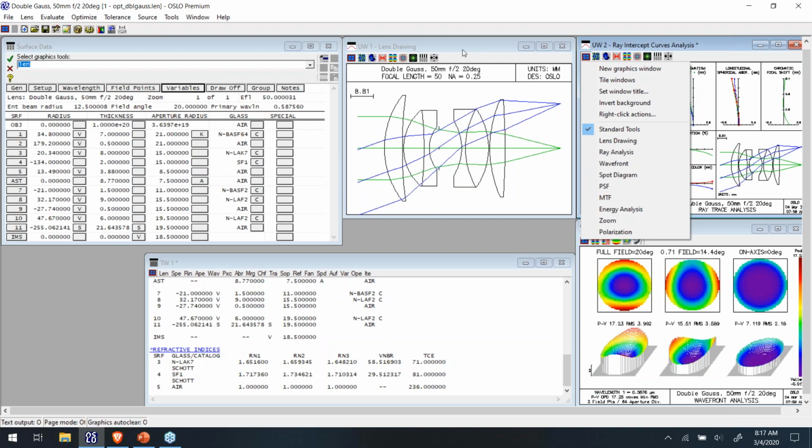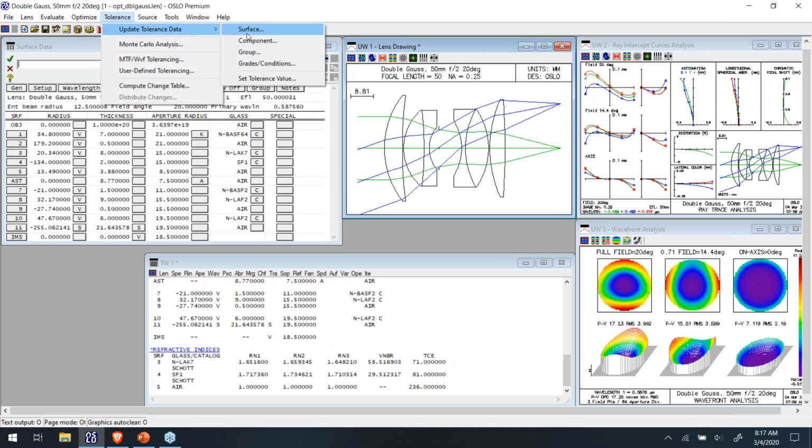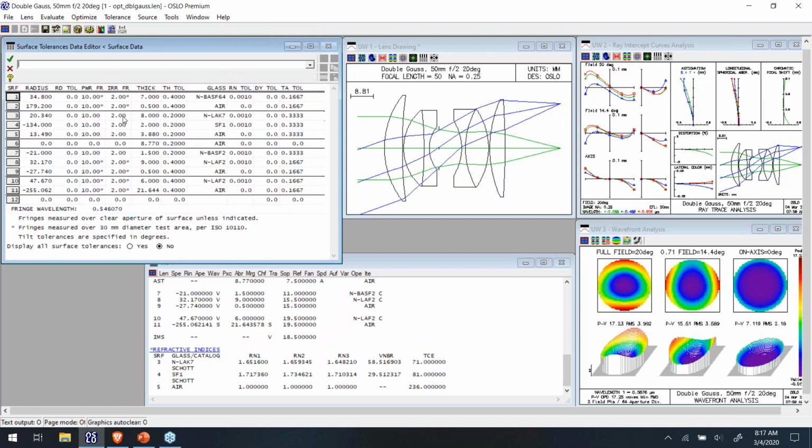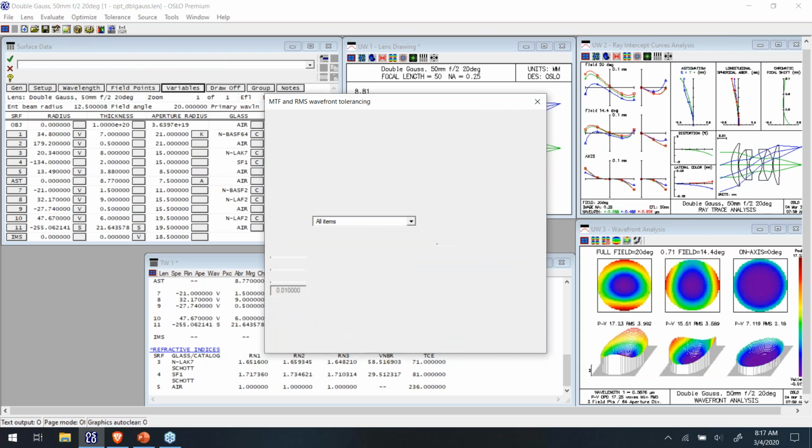There's an enormous number of analysis options that you can see through the graphics window here for many, many different types of metrics. And additionally, we have a lot of those here in the menu. The tolerancing tools are quite good. It does have some wavefront differential capability, which is the Hopkins-Tiziani followed on by Chuck Rimmer's work. So it's quite good at different tolerancing steps. There are some spreadsheets in here that work on different sort of tolerancing factors. Right now, this one hasn't had numbers assigned, so it's set up to some old ISO 10110 default types of numbers.